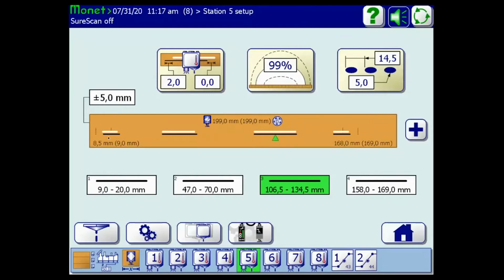So the programmed events are normally black. But if you ever see it turn blue, the system is actually telling you, well, you're running so fast that I'm just going to spike the valve and use what we call a spot option, or spot output, as opposed to a line event output. And the system will do it on its own. It's intuitive enough to know the math on when it's running too fast to be able to spike, hold, and then stop. Even though we're not using the spike on your specific valves, it'll just know when it needs to change that very short line event into a spot event.